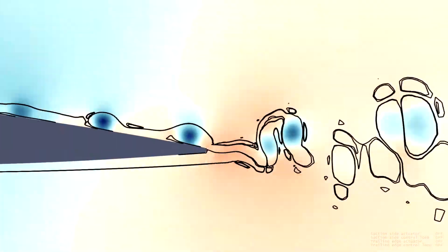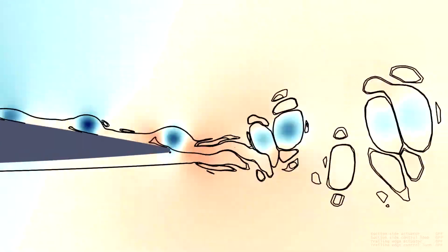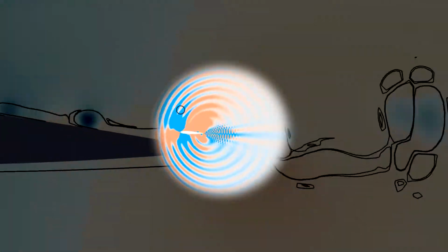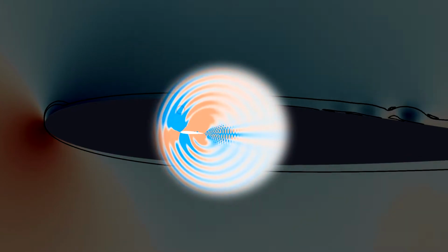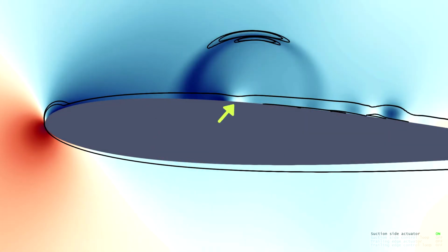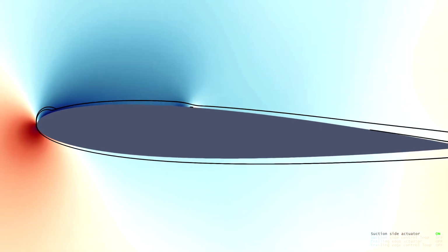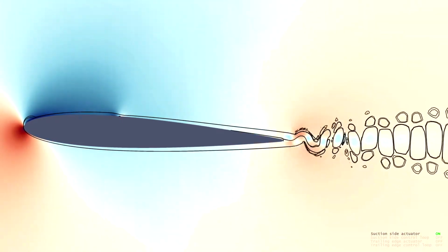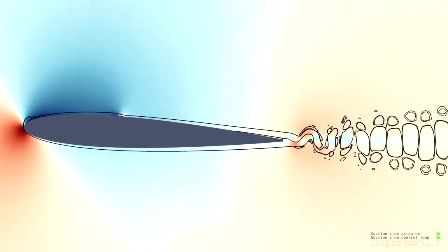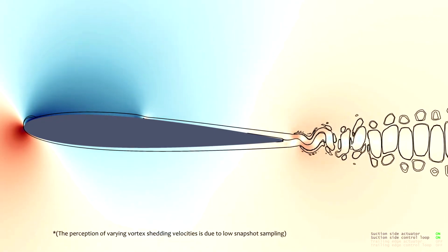We can see the formation of coherent structures at the suction side. That's the position where we take measurements, and that's the initial position guess for the actuator. The ESC loop perturbs the actuator around its central position. The integration pushes the actuator towards the center of the airfoil.